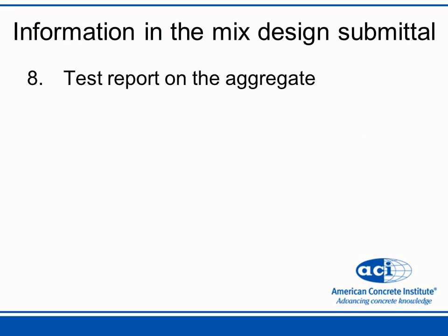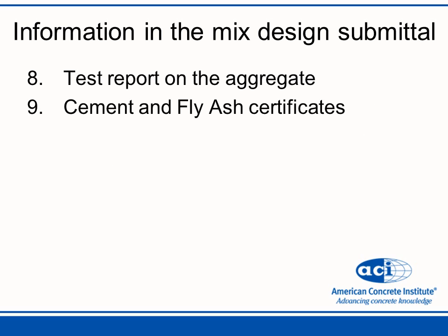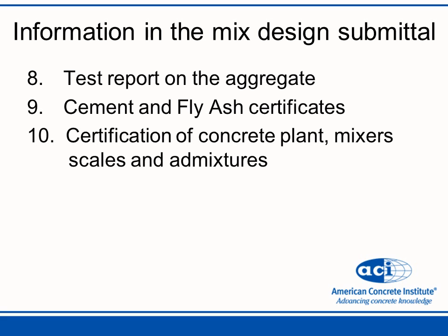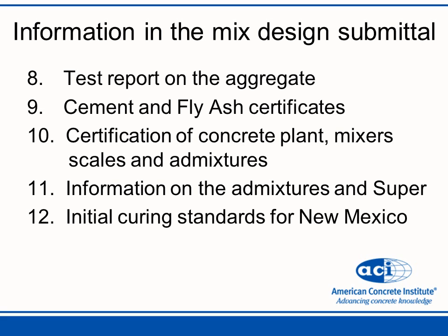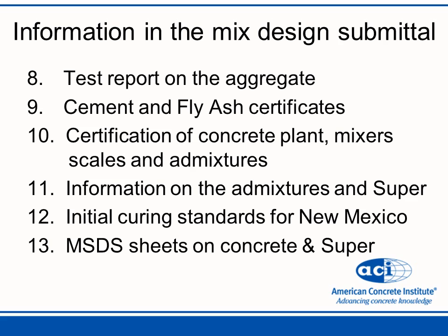We also want to include some test reports on the aggregate, the cement and fly ash certificates, certifications of the plants and scales, information on the admixtures, initial curing standards, how the cylinder should be cured. In this case, it was for New Mexico, along with the government required MSDS sheets for the mix design submittal.